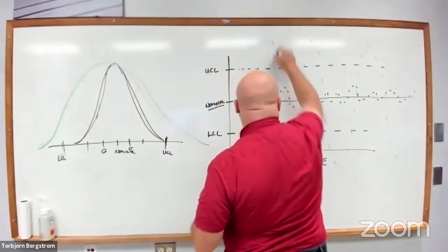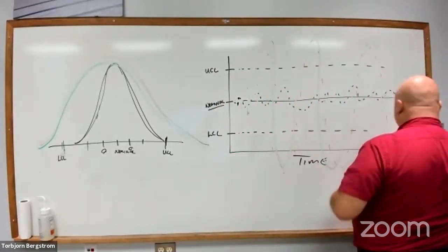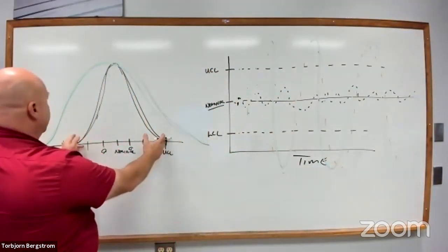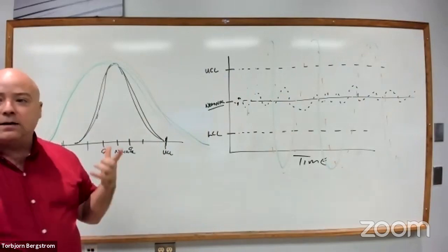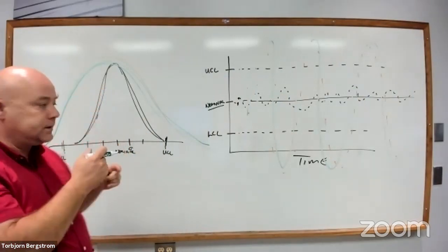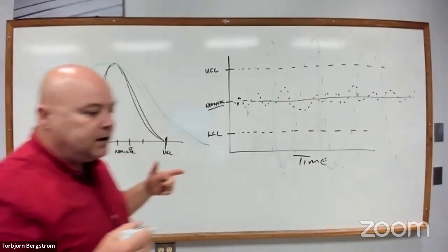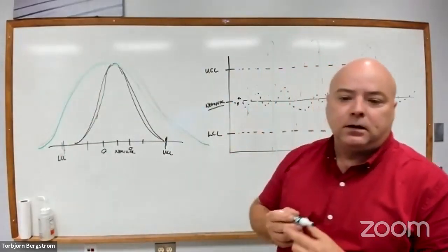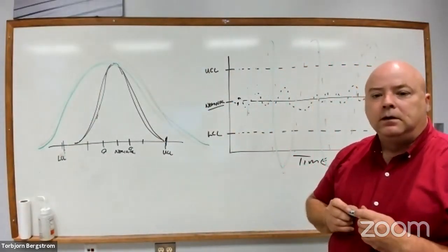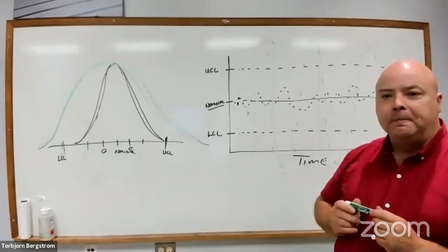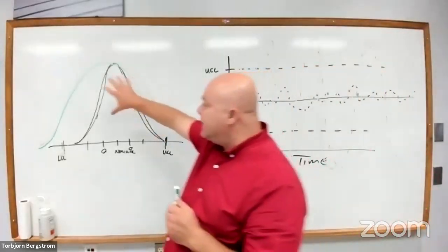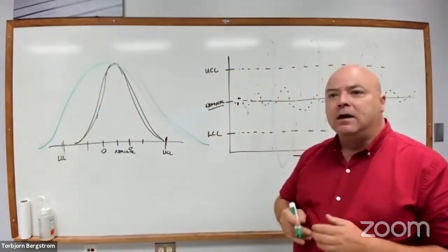So the green line, our control chart, we expanded outside our control limits. We're outside our control limits here. Now, our process still makes some good parts. In fact, it makes mostly good parts, but enough of them are outside. So what do you have to do in order to still ship your parts to your customer if you have this experience? Test more of them. You have to measure each part before you ship it, right? So you ship the good parts, you scrap the bad parts. So in this situation, you can still ship parts to a customer, but it's much more expensive.